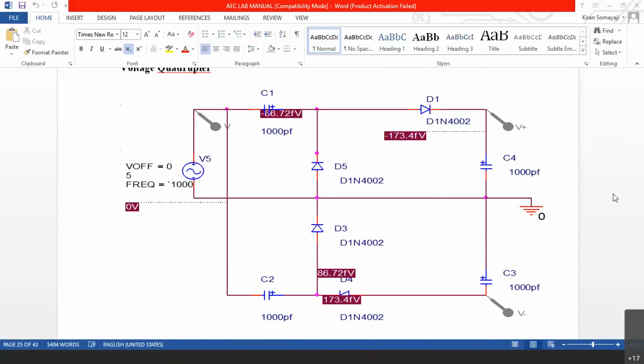As long as you do not connect the load. Load should be very less here. In the sense, we cannot connect a heavy load to the circuitry. If you have to connect a heavy load, the value of the capacitor must be increased. We are now using only 1 nanofarad here. If it is in microfarad, it can supply current also that way. It will remain charged. So it is possible.